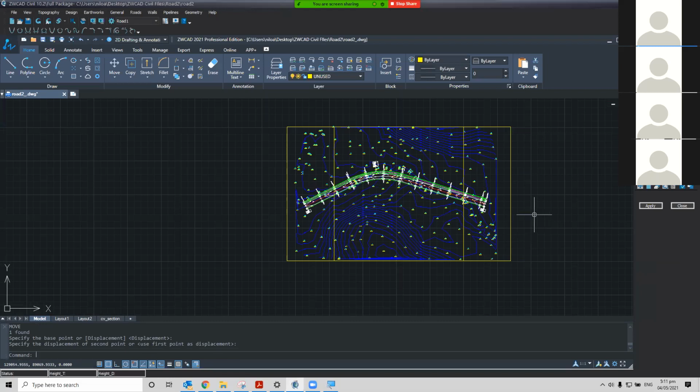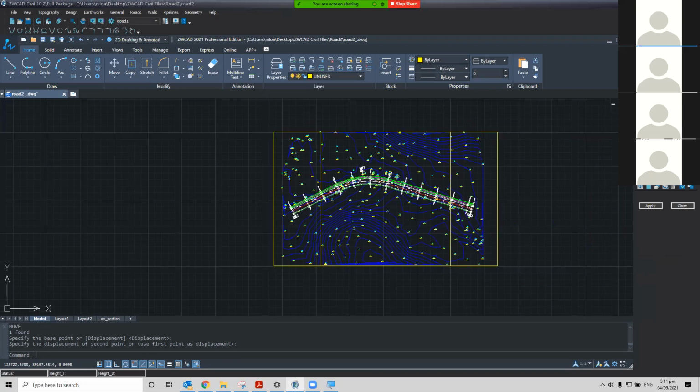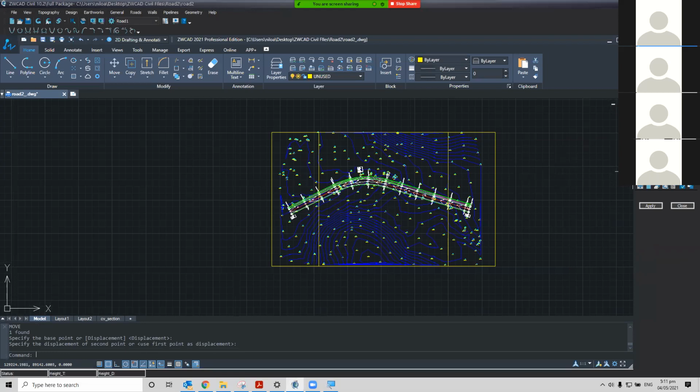So now you start designing the frames division. For now it's only polylines. Now let's define them to be frames. How do we do it? You are now on the first frame. Select the first frame, and press enter. You see what happens? See on the right window: base first, base second. Yes, these are the definition of the first frame. The software picked it from the polyline.